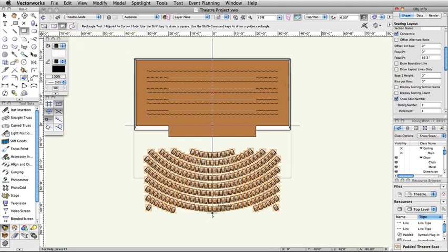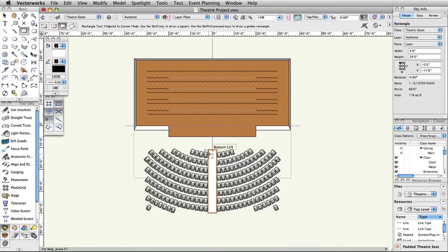Click once at the bottommost point of the center guideline. This point will be just below the bottom center of the seating layout. You may need to use the snap loop. Move the cursor up and then press the Tab key to enter the floating data bar. Set Delta X to 2 feet, press the Tab key, set Delta Y to 29 feet, and press Enter or Return twice.